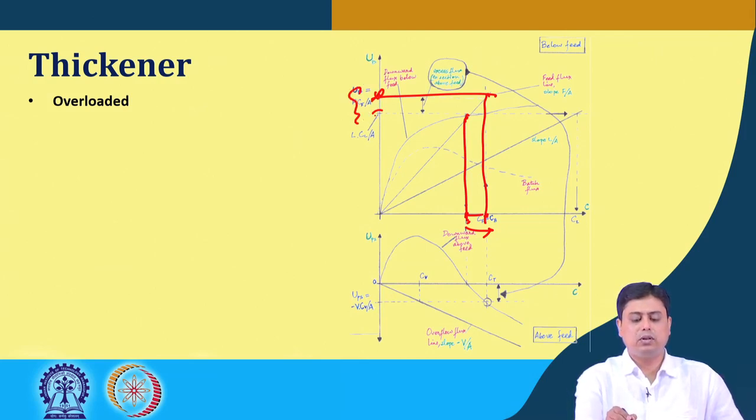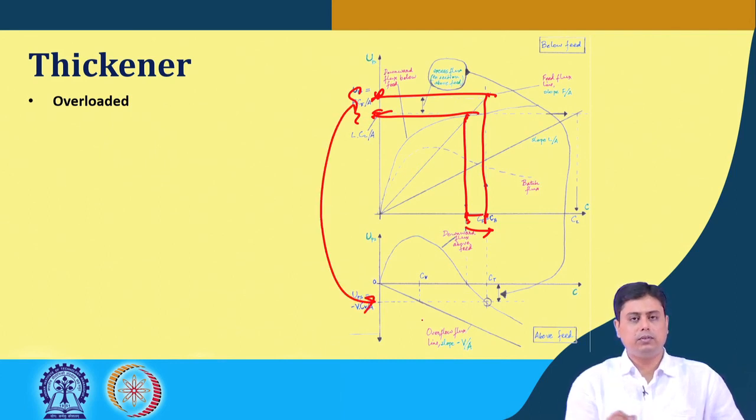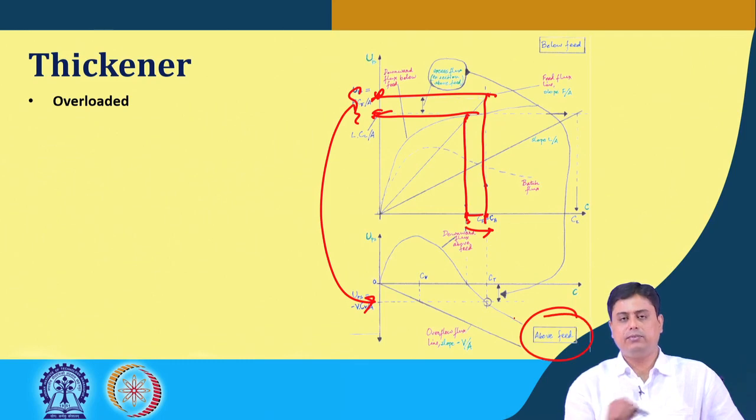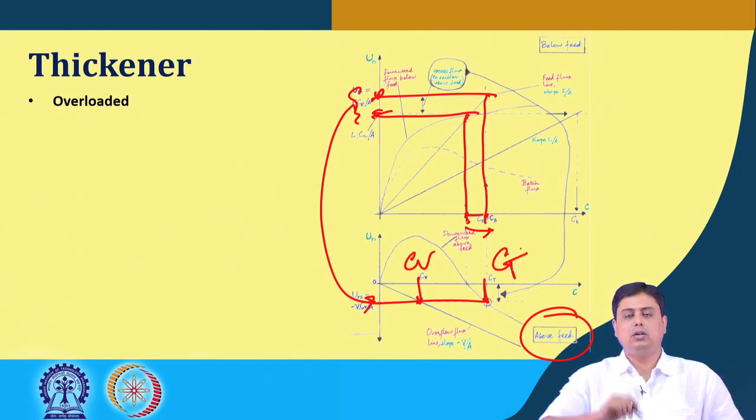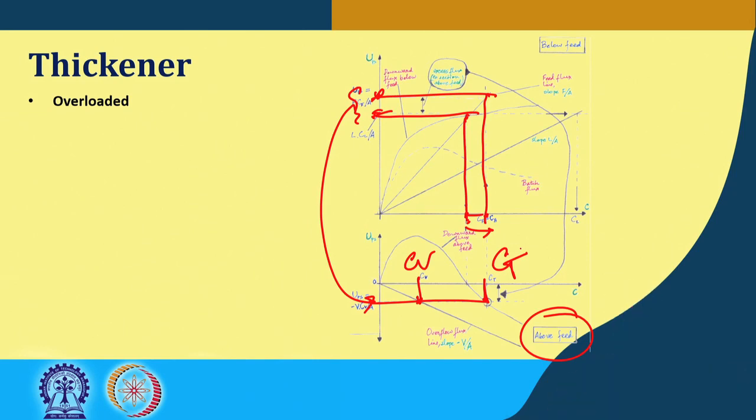what the difference is between the actual flux and the critical flux, and that is added at the bottom or, say, above the feed under this flux condition, and we find out the corresponding V, Cv and the mean concentration at the top region. So this is how we use this information. If the problem is given in such a way, these graphs are helpful in calculating those concentrations.